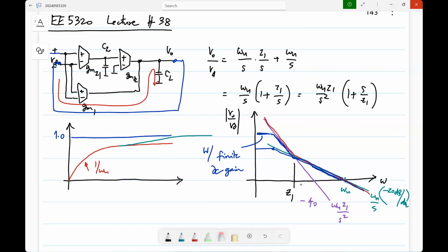You shouldn't go and change every other characteristic of the op-amp. Now, if you change CC, yes, it will change the stability, but of course, GM1 by CC is the unity gain frequency. So, to a first order, if you change GM1 and CC in the same proportion, all other things will remain roughly the same. Of course, we know it doesn't remain the same because even the non-dominant pole expression has CC in it, right?